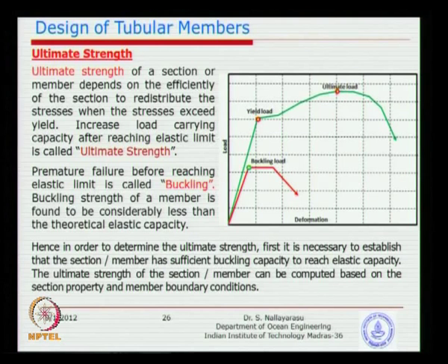That is what everybody thinks, just simply make the size of the column smaller. But then unfortunately what happened, we have selected a high strength steel, very good steel, 350 megapascal, but the size was made so small, we are not able to utilize the full yield strength of the material. You have only used up to maybe 100 megapascal. So what is the purpose of buying a high strength steel and then not using the strength, but we allow the structure to fail earlier because we made it too slender.